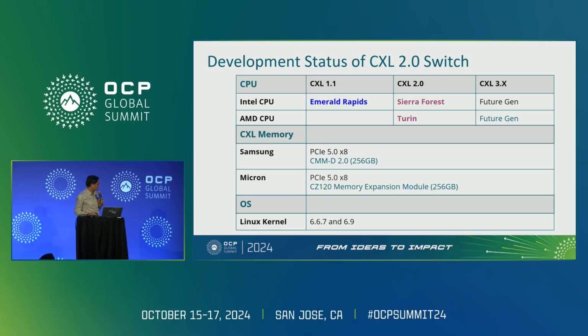We use the AMD Turin servers, and the Turin server can see the virtual device that we create with our management CPU. Currently we have 4 devices or 8 devices. Then we bind real devices, real CXL memory modules, to that virtual device to do the access. Next time I will bring up the real CXL 2.0 implementation and get some of the data.